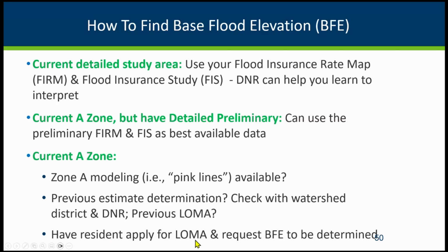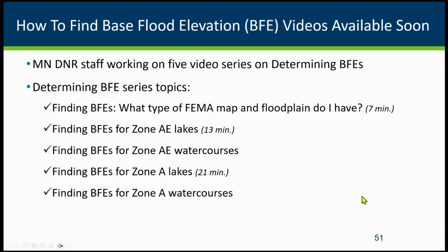Or sometimes we can have someone apply for a letter of map amendment and say, hey, we checked with everybody else. There's no data available. Please calculate an estimated base flood elevation for this site. And FEMA, the contractors that do the LOMA reviews, will calculate a BFE if it's for an individual property. They won't do it for subdivisions.